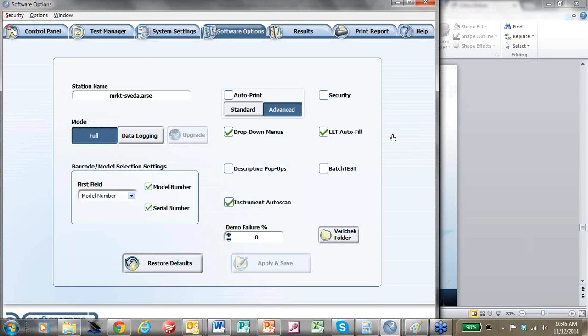As you know, for the touch current testing, there's many different scenarios that the medical device industry guys like to test. This option allows, instead of them setting each and every fault condition manually, this basically populates all those different types of tests for the user. So that saves a lot of time.